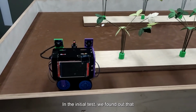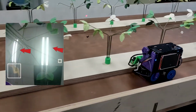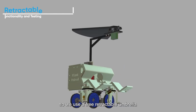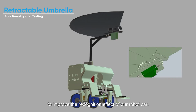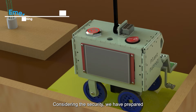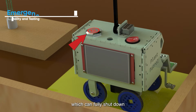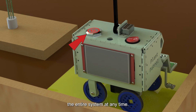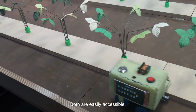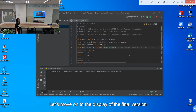In the initial test, we found out that a strong light source above will affect the recognition. So we use a retractable umbrella to improve the recognition effect of our robot car. Considering safety, we have prepared a start button and an emergency stop button which can fully shut down the entire system at any time. Both are easily accessible. Let's move on to the display of the final version.